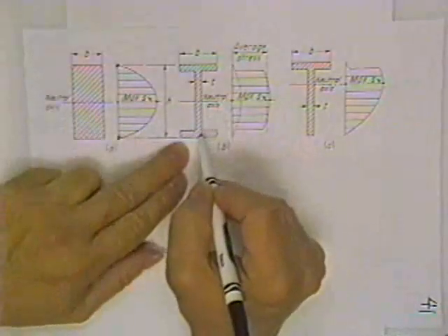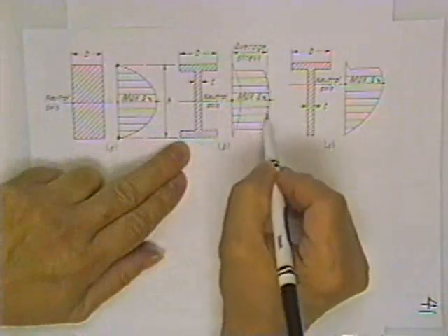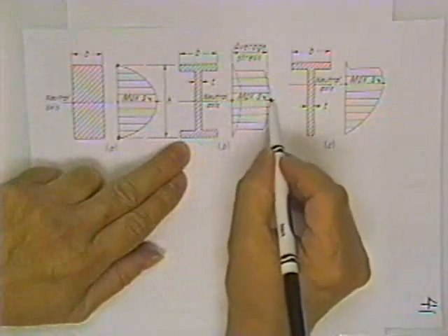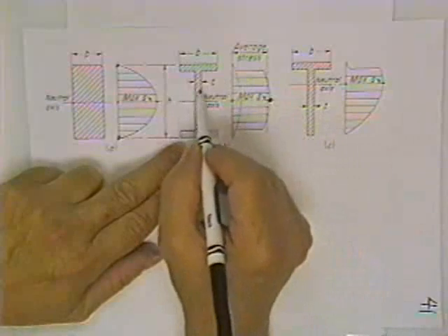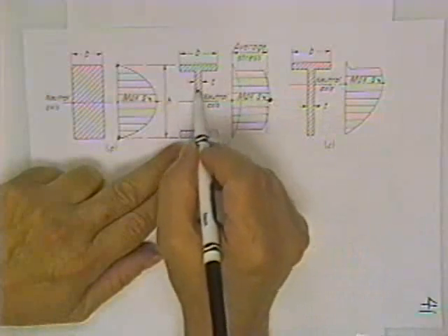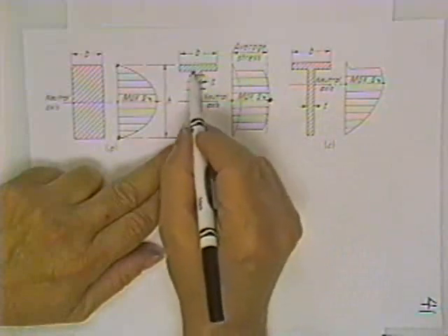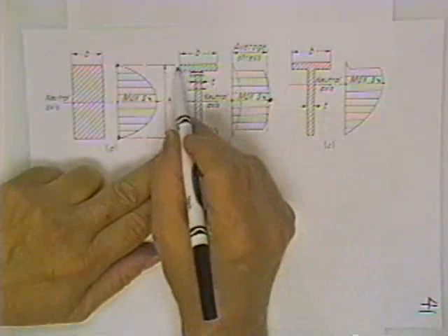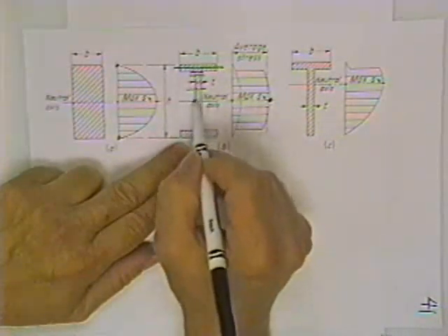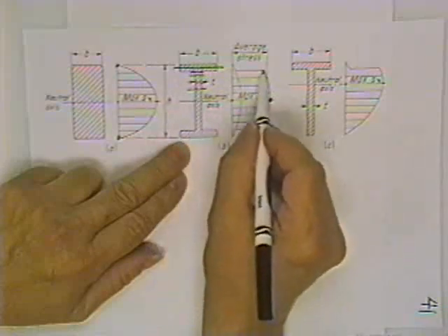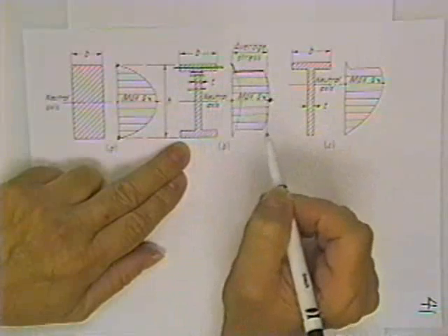Now, for a wide flange, the shearing stress is still distributed parabolically. It's still a maximum at the neutral axis, but right in this region here, when you divide by the thickness of the beam, you're dividing by T. Divide by T, divide by T. Now all of a sudden you divide by 30T. Probably 30 times wider up there than it was there. Therefore, the stress drops off dramatically and continues on its parabolic way.